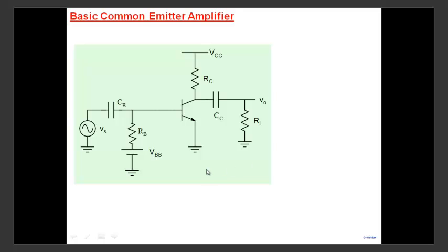All right. So let's come back to our basic amplifier, the common emitter amplifier here. We've seen a little bit about this amplifier, but let's go into more detail. We would like to calculate the voltage gains. Two voltage gains: when normally there would be a load, we call it AV, and AV0 is what we call the open circuit voltage gain when RL is infinity. Rin and R0 have to be calculated. Rin means the input resistance looking from here, and R0 is the resistance looking from here. Note that R0 excludes RL, and is the resistance looking from this side here. So we need to calculate these two.